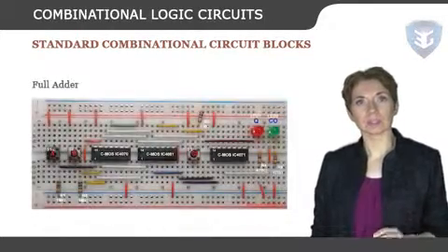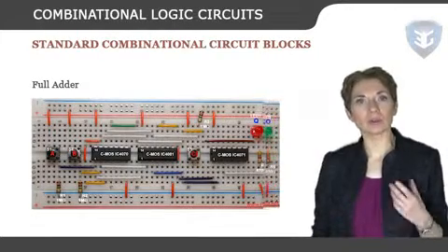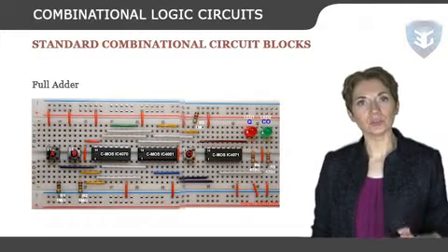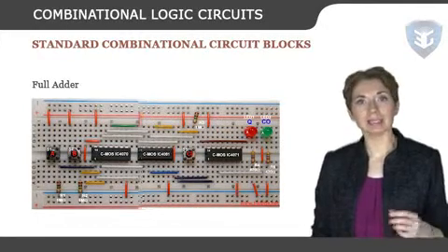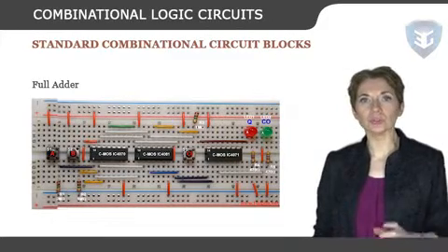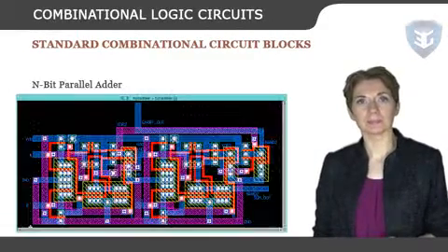Full adder. Full adder is developed to overcome the drawback of a half adder circuit. It can add 2 one-bit numbers, A and B, and carry C. The full adder is a 3-input and 2-output combinational circuit.